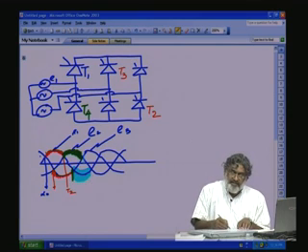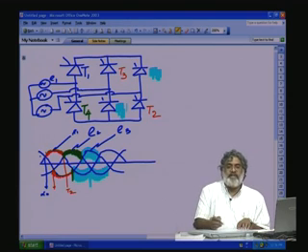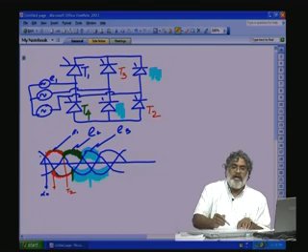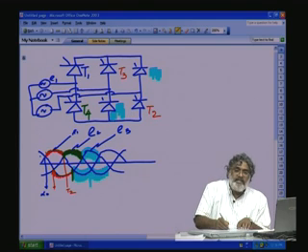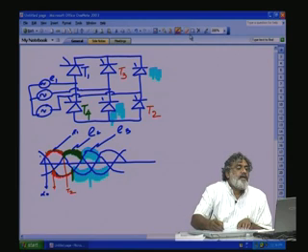Now, again after 60 degree there is a conduction initiation required at E3. E3 becomes more positive than E2. So, T4 is our next, the next positive side will be T5. Then last, E2 becomes negative, that is from this portion onwards, that is T6. So, if you see the sequence, 1, 3, 5 on top and 4, 6, 2 at the bottom. So, the next phase will be, I will just clear this part.